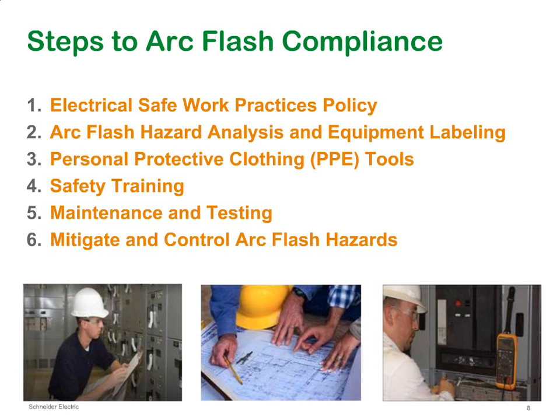So we have to have personal protective equipment available on site. The owner of the facility must provide that to the workers. There must be insulated tools provided to the workers who are going to be working on equipment that would potentially put them in a hazardous condition in respect to electric shock or arc flash. And these items of clothing and tools need to be acquired and need to be provided.